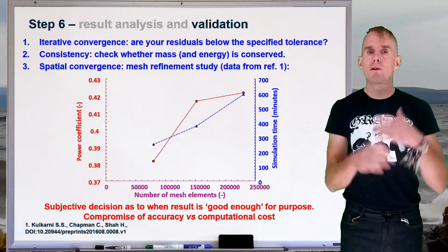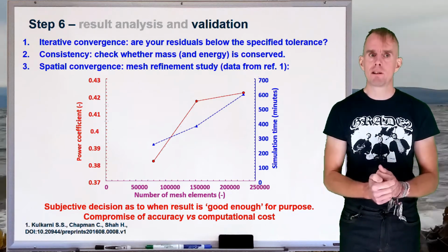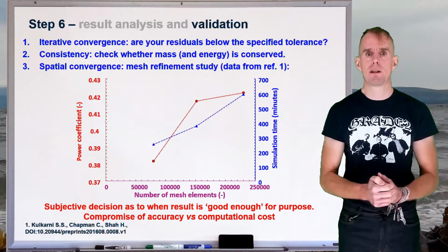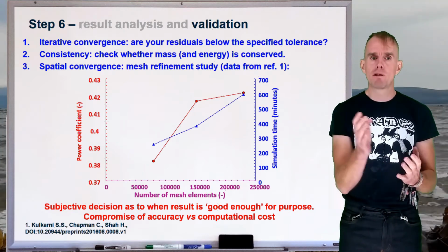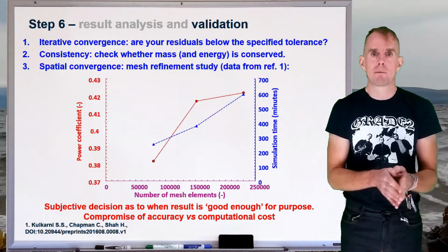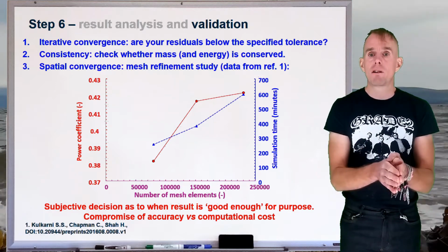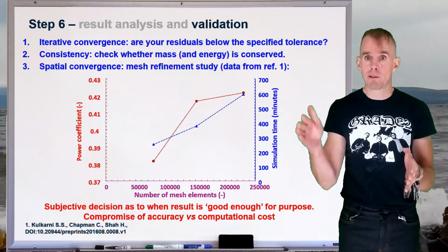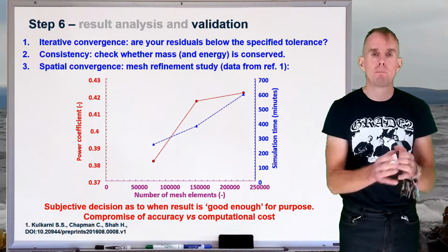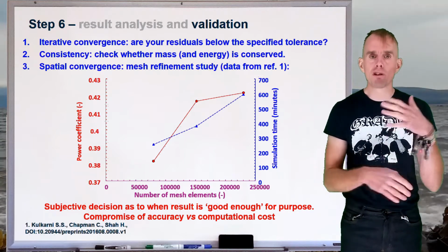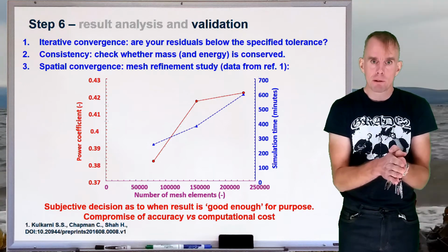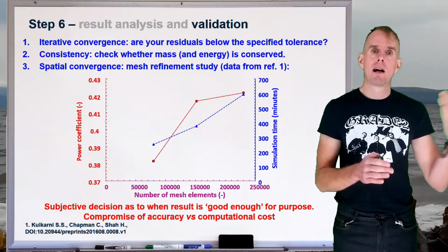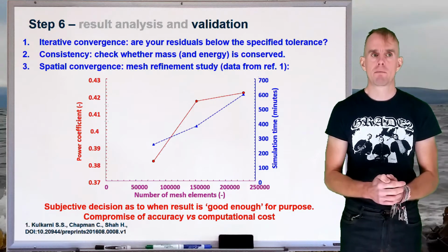However, if you're doing parameter sensitivity studies, you don't want to wait days for each solution if you can possibly avoid it. And so you need to be able to choose a mesh, say, that will give you something within 5% of the answer that you'd get with a very fine mesh, but maybe with 1/10 of the computational time. Once you know what those errors are, if there's a particular solution you want to explore in more depth, you might run that as a special case on a refined mesh.